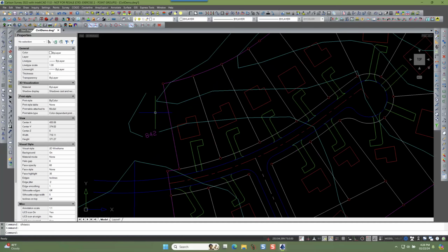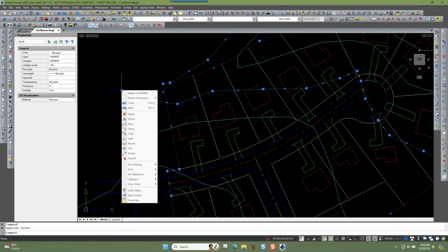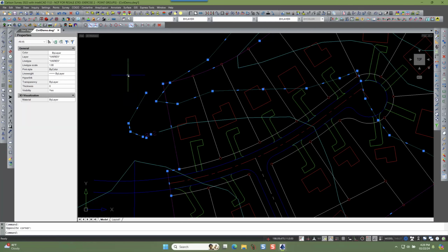So in the AutoCAD world, and I'm not sure what your OEM version does, but in full AutoCAD, there is a command or a menu choice. If you select a couple of things and right click, you'll see a command that says isolate objects. Then you can pull that to the right and it says either hide or isolate, and then end object isolation. That's part of standard AutoCAD.